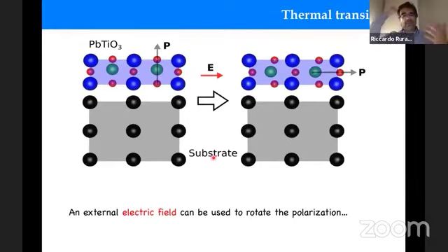So if you think a little bit, in the first set of results, I was applying discrete pulses of electric field to stimulate commutation events of the polarization. I wanted to reverse the polarization from here to here or from here to here, but I just needed pulses, okay? Strong pulses, because you need a strong electric field to make this happen. The coercive fields are high.